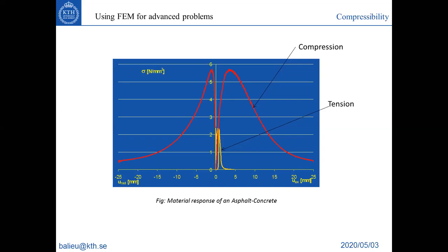The same in tension. If you identify the peak stress with a tensile test, you will get this point. If you use a simple yield surface with only one parameter and afterward simulate this in Abaqus, if you model a tensile test, you will be able to reproduce this curve.